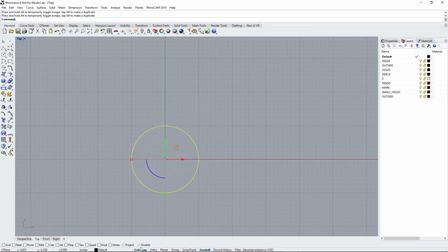And I've got grid snap turned on down here, bottom of the screen, so it's snapping to the grid. And if you recall in our setup, we set the snap to 1/16 of an inch, and each one of these small squares is an eighth. So that would move it up in the Y 1 inch and over in the X 1 inch. And that's a 2-inch circle.